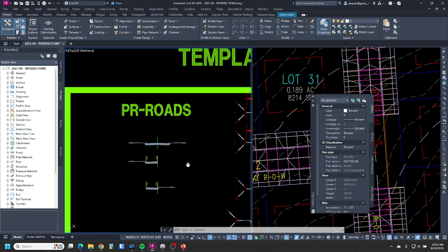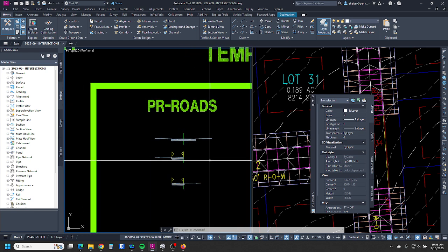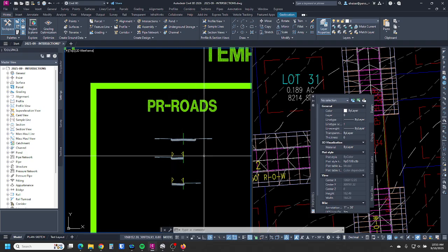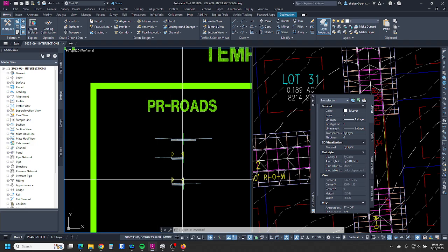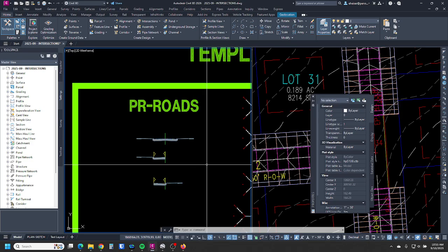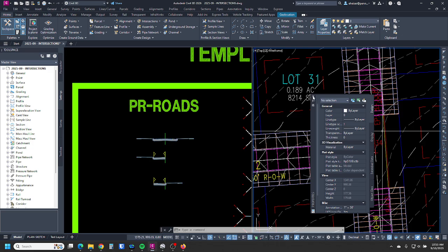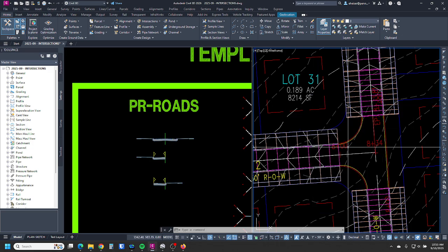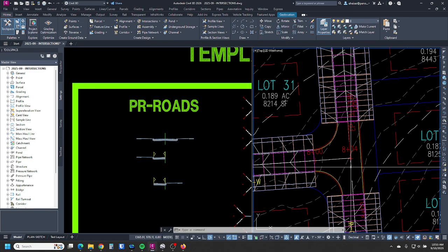So I have a project that I did and had, I believe, 5 intersections. I was able to reuse all of the assemblies, and it made it not too bad. It actually made it a lot quicker whenever I needed to do an intersection because I already had things created. It was quicker than grading it by hand. And it could be incorporated into the surface as far as doing spot elevations, which was nice.